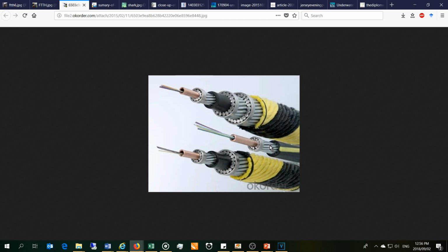And because it is wired like this, it does have some flexibility, but remember that we should never bend fiber optic cables with harsh bends, because the light rays will then be interfered with. So we do gradual bending with fiber optic cables.